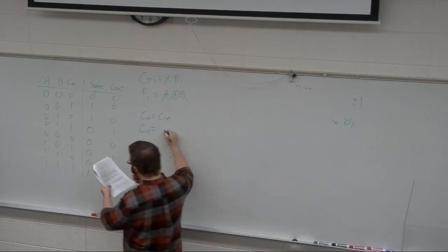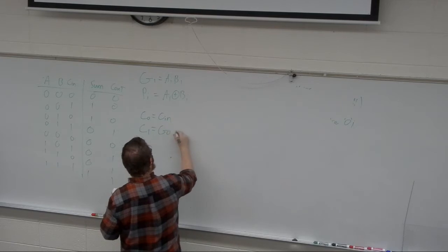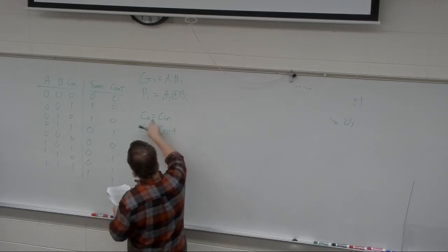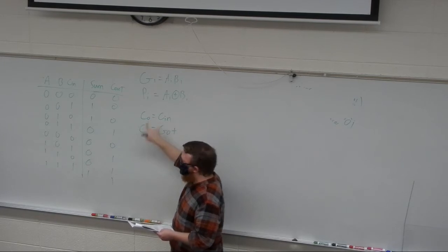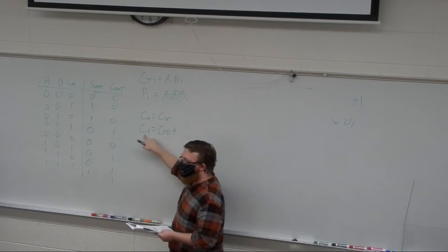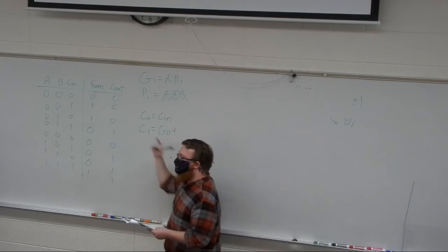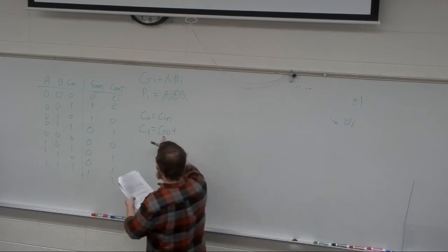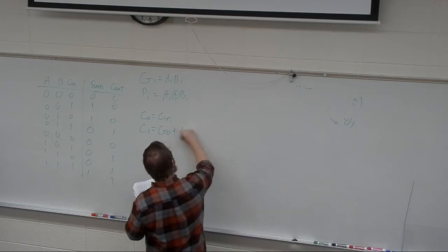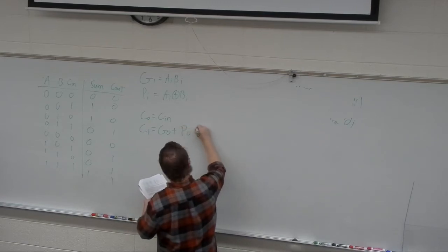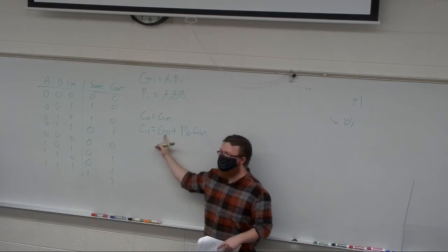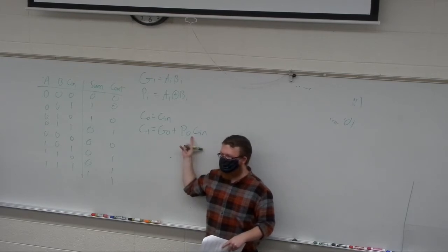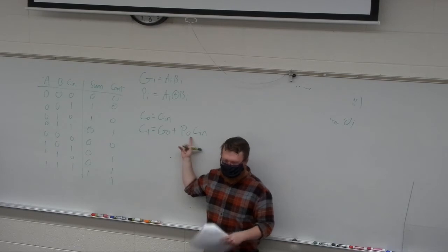So now we might generate a carry. So this is tied to the first input. This is, does the first adder generate an output carry? So do I generate it, or do I propagate it from the input? Right, that's the way I get a carry, is either I've generated it or I propagated it through. There's no other way to get a carry.